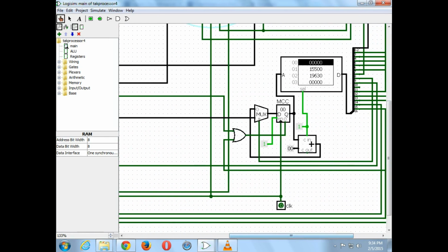which is the microcode mechanism. The microcode mechanism is basically really just like a music box. You know how in a music box you have all those pegs, and when you wind it up and let it go, it will slowly rotate the drum, and the pegs will play the individual pieces and make the music. It's the same thing here, except you're looking at individual bits to turn on the output enable here and clock here, turn off the output enable here, turn on the output enable over there. So it's like the conductor.